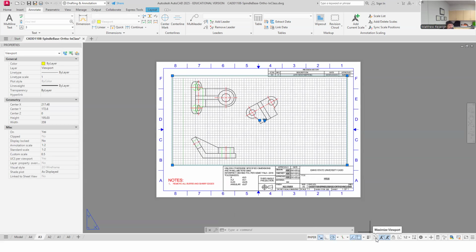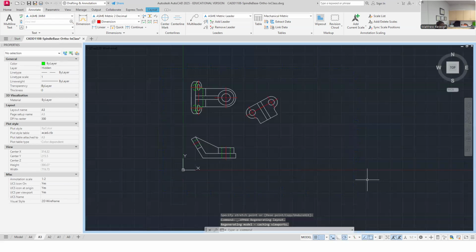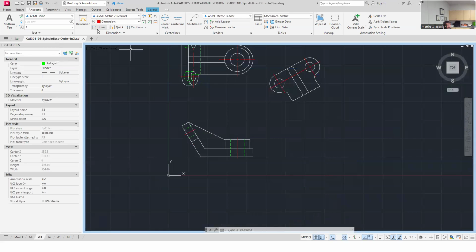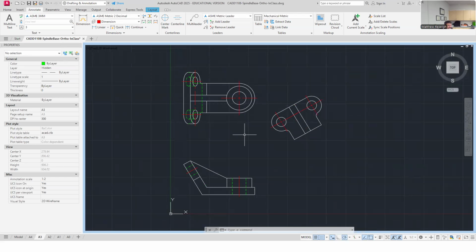But we'll cut them up as I organize my dimensions. But I'll get in here and start dimensioning. So I'm just gonna start with my overalls. Overall height, width, depth. So I'm gonna kind of proceed where I'm gonna put every dimension that I can get on the top and front that is true to length and easy to understand. I think I'm going to put it there. And then I'll hold off on my auxiliary view for mostly the primary stuff that was distorted in these two views, and I'll pick up their dimensioning over here.